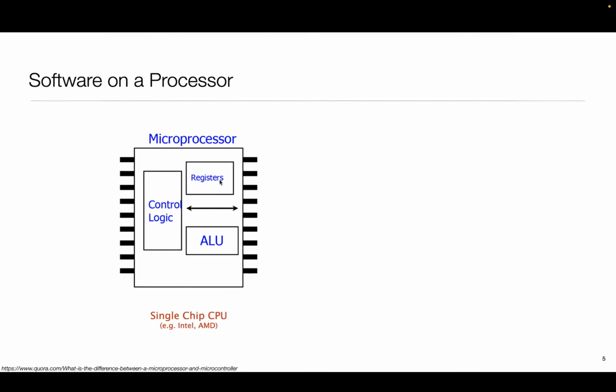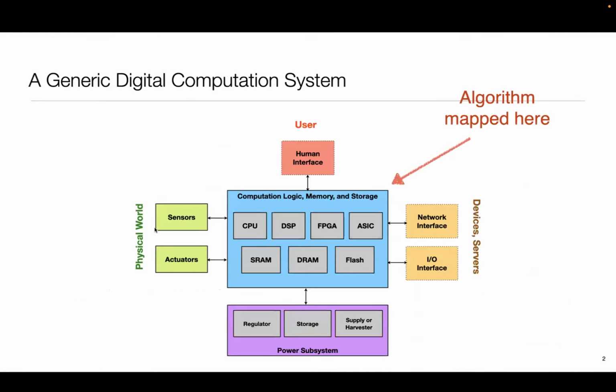So if you come to storing information, if I go back to this hierarchy that I had before, you can say to the left of SRAM are registers. Registers are super costly, super fast, can be on chip. SRAM, less costly, less fast, can still be on chip in modest quantities. DRAM, we can make in huge quantities, much slower, hundreds of nanoseconds type time to access. You may put it on chip in some cases, but pretty rare. And then flash, again, you may put on a chip in some circumstances, but typically off chip.